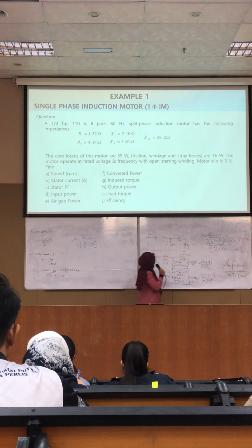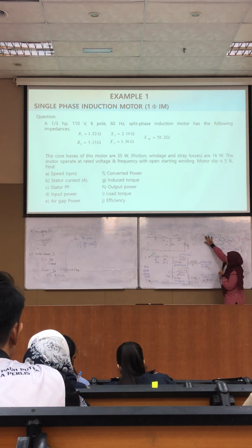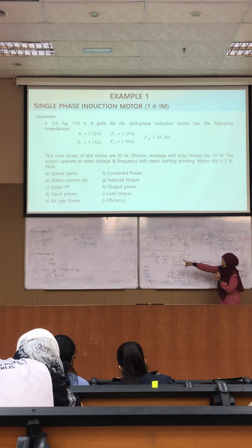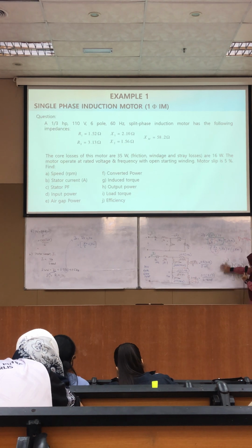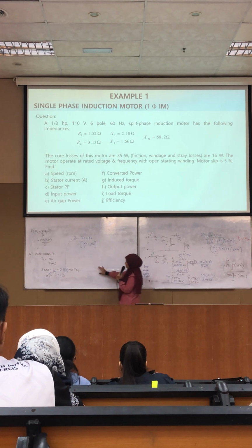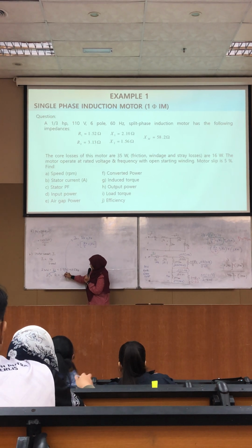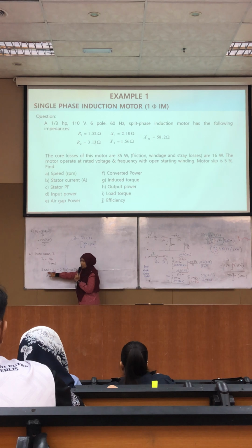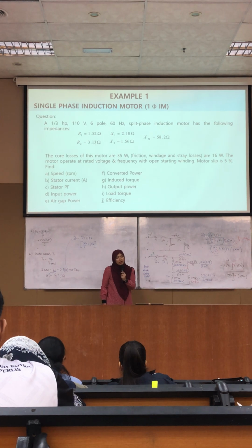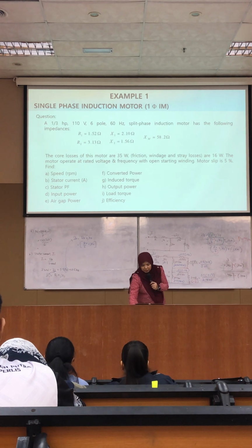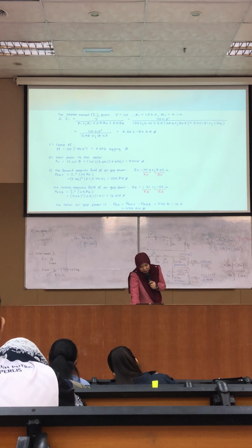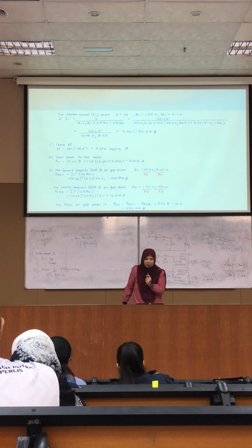Okay, doing up to here is fine. So the ZF here is from this equation, inserted from here, and the ZB is from the one I erased earlier. So put the total in this, then calculate the total impedance for the stator current. Okay, the answer is in the slides, right? You can check this one. By right, you should get 4.66.